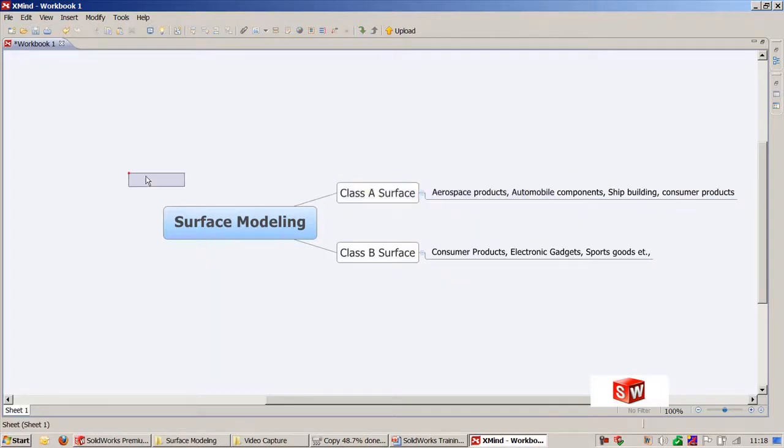But in general, if you look into surface modeling, we require the surface to be smooth. It should have only tangential or curvature continuity, and nowhere should it have a sharp corner. That's why we are getting into surface modeling. Creating a surface model does not follow a specific rule. With respect to the available data, you can create it from existing images.